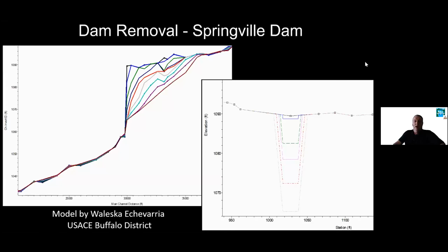And what you can see here is the time series of erosion after the dam is taken out. And one of the things that we have in RAS is you can use the classic veneer model that we use in 1D that reduces the whole cross section at once. But we also have this simplified channel evolution model that forms a channel that goes down and out, more like a rapidly developing channel in a flush or a dam removal would do. And this is really helpful.